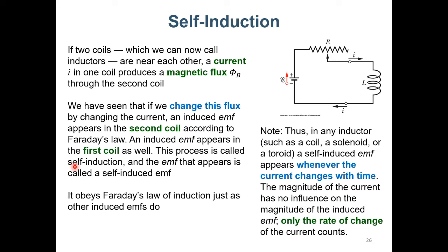So there will be net flux, or suppose this is a constant current and you move this one close to another one, so that the magnetic flux for this inductor is changing. So there will be EMF, and as long as there is EMF, there will be some current.